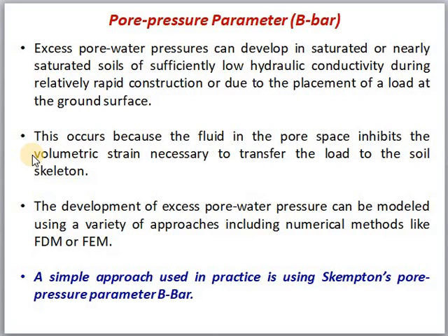And this excess pore pressure development can be modeled by the finite difference method or the finite element method. Nowadays we are using the finite element as well as the finite difference methods, but there is an approach which was found years back by Skempton, that is using the pore pressure parameter B bar. That is, how will you find the excess pore pressure in the field. Based on some experiments he has arrived at a pore pressure parameter.